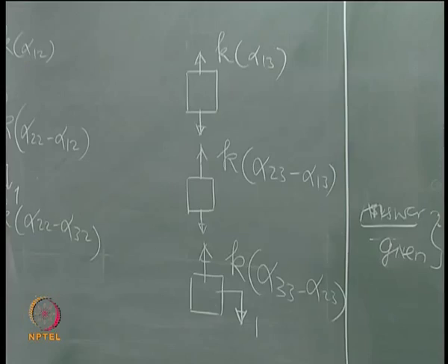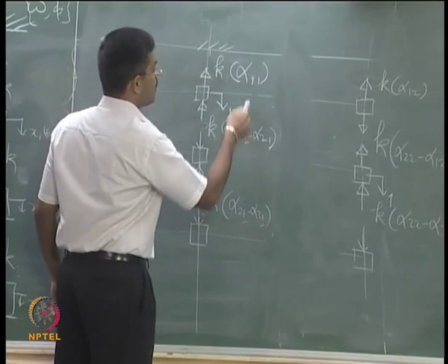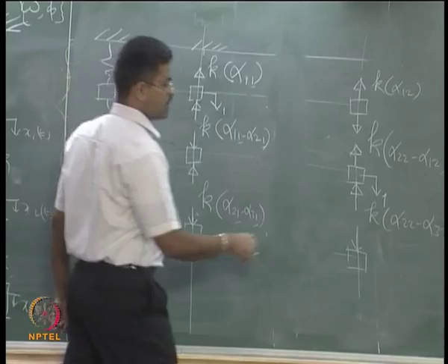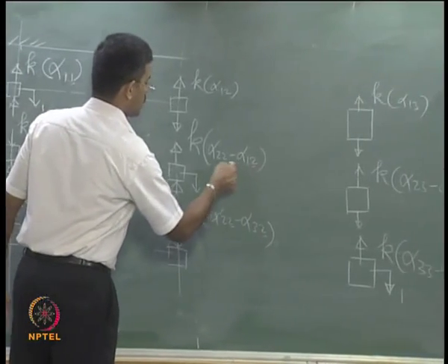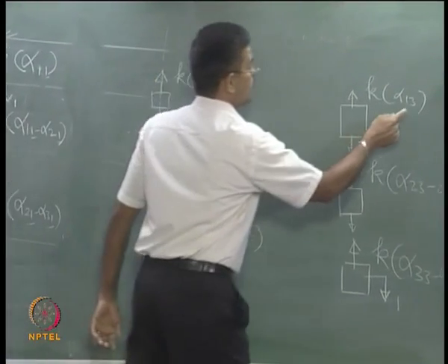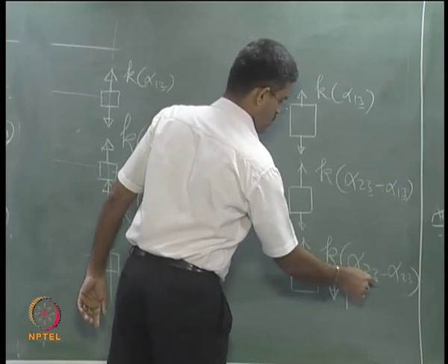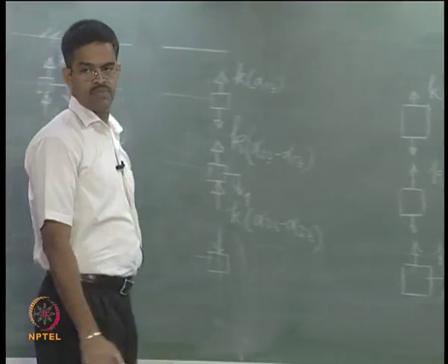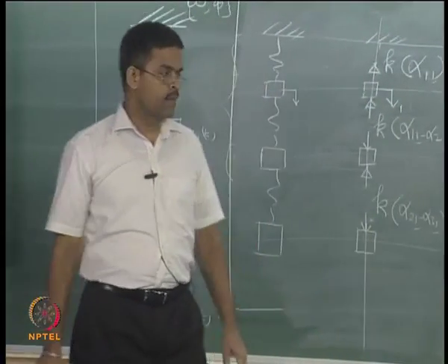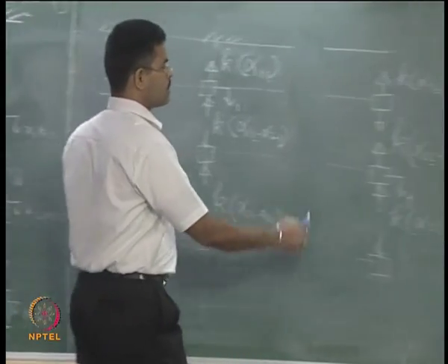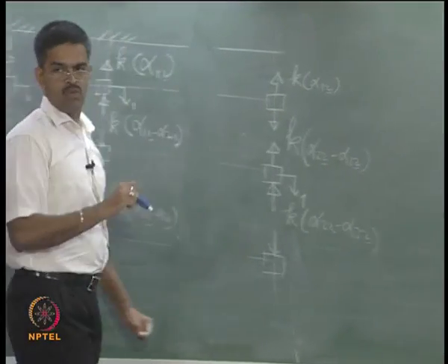So in this, very interestingly, all the second subscripts that you see here will be related to the point where you are giving your unit value. All the first subscripts will be at the point where you are measuring it.